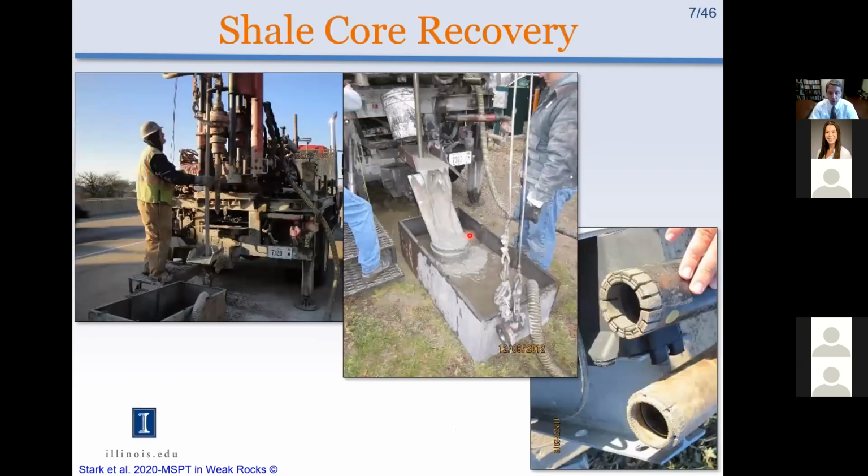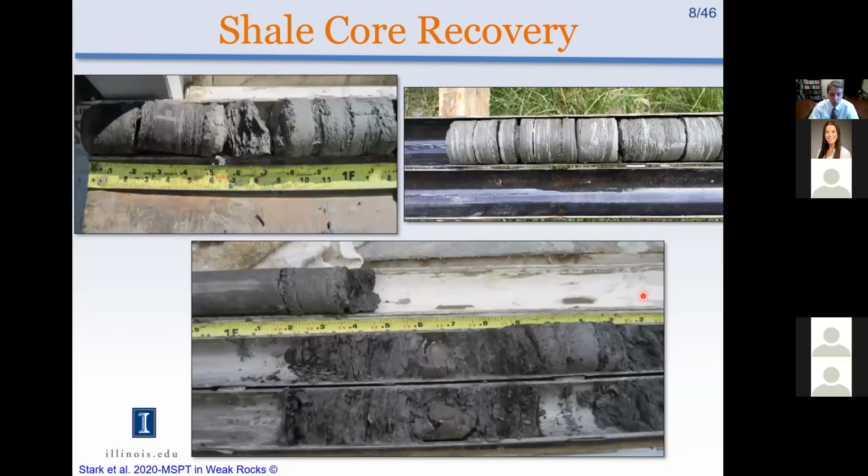Before the project, IDOT would frequently have a shale core drilling program that looks like this. The diamond bit core barrel is over here on the right where my pointer is. It's used to drill out samples of the shale, take those to a laboratory, and try to measure the unconfined compressive strength. Unfortunately, with shales and other sedimentary rocks, they can break during the drilling and sampling process.